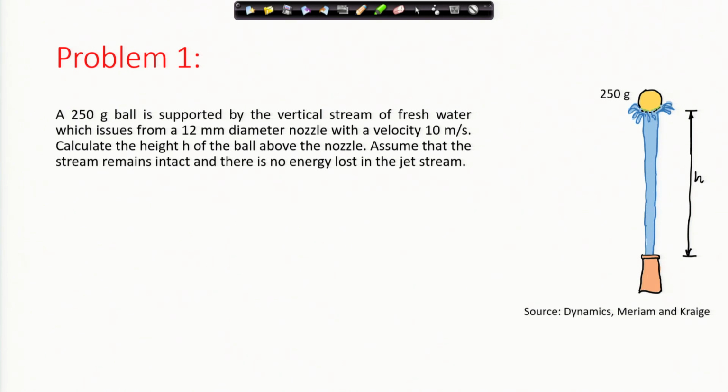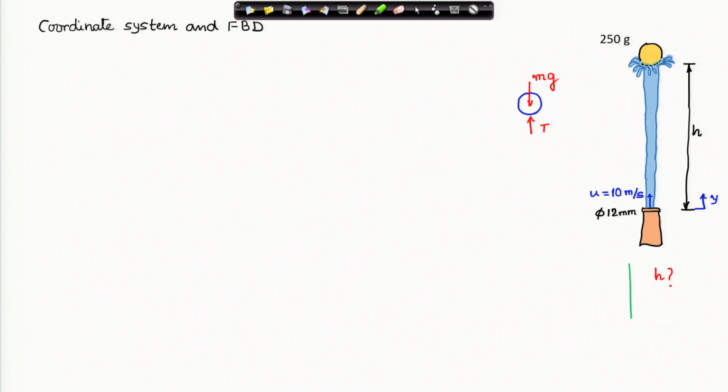What is happening? The water particles are going and hitting and transferring momentum to the ball. And because of flow, as we have just now analyzed, because of mass coming in and hitting it, there is a definite force. We have calculated this force, and that is what we are going to do. We will consider our system as this ball and a little bit of its surroundings, so that we allow this water to come and enter our system.